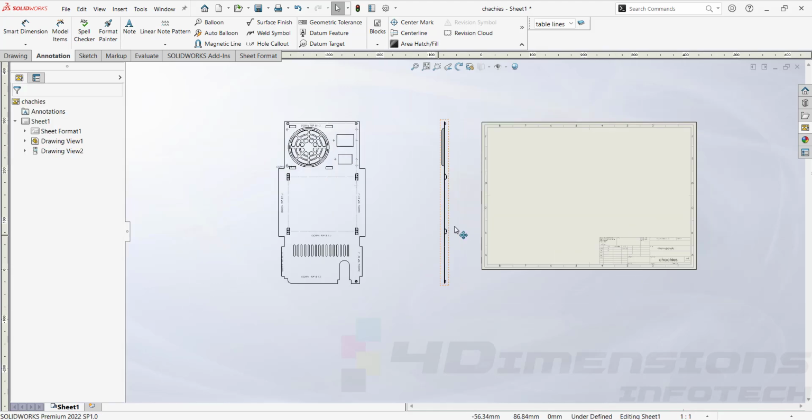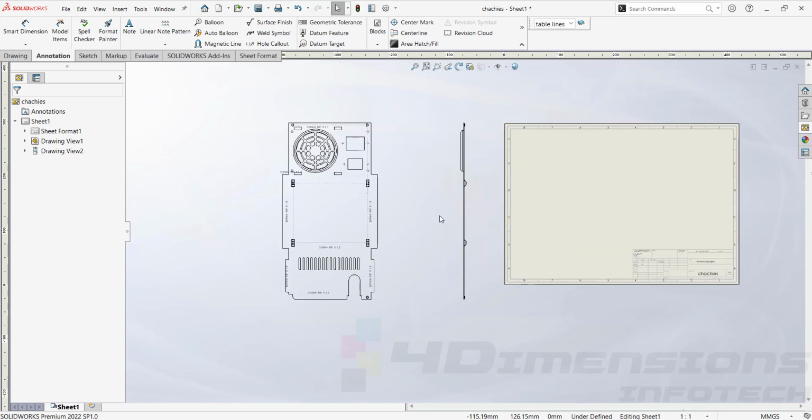And for laser cutting drawing, I need to convert this drafting file to an AutoCAD file so as to give it for laser cutting. Any part that is being transferred to AutoCAD should be transferred by a drawing, and it should be in scale 1:1. We also need the Weldment's file there for the laser cutting. At that time also, from drafting to AutoCAD conversion, the scale should be 1:1.